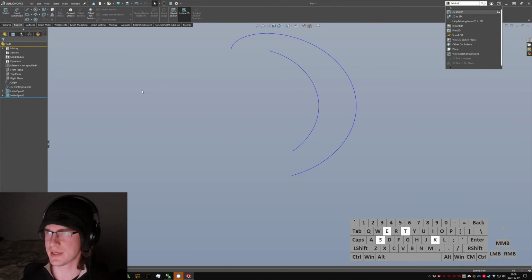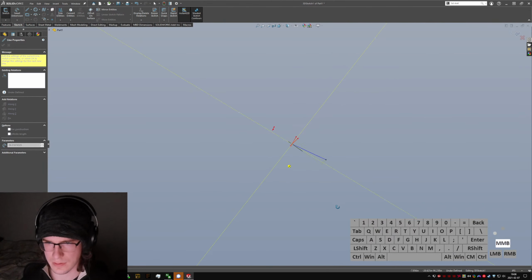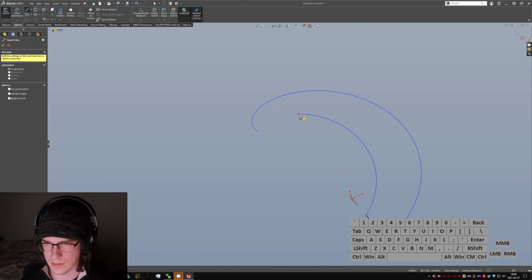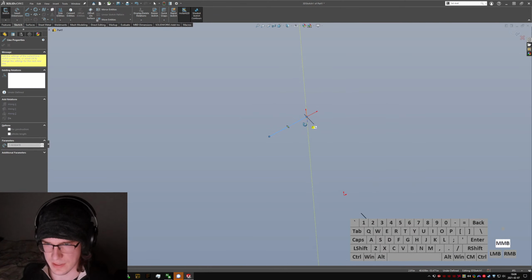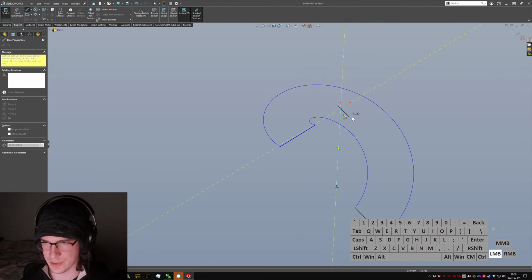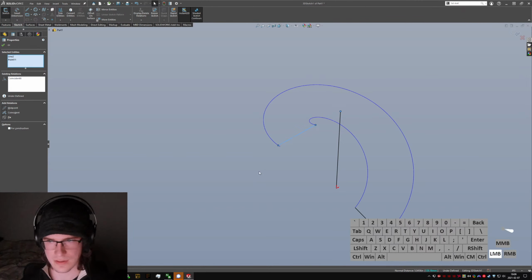And 3D sketch. Just gonna draw lines between the end of these. Coincident? Is that gonna fix that in place? It does. Nice. And it doesn't look like it wants to let me easily select. So I'm gonna have to draw a cheater line here and make this guy coincident with this.